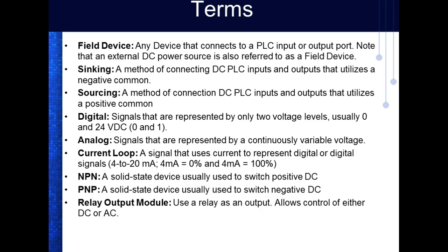Sinking is a method of connecting DC PLC inputs and outputs that utilize a negative common. Sourcing is a method of connecting DC PLC inputs and outputs that utilize a positive common.